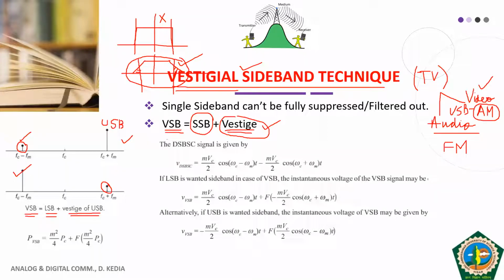So if we have to survive with a non-ideal filter, then obviously in pure form, we cannot have SSB. So in VSB, what we do, we tolerate, or we send, a small portion of the other sideband also, instead of completely removing that.